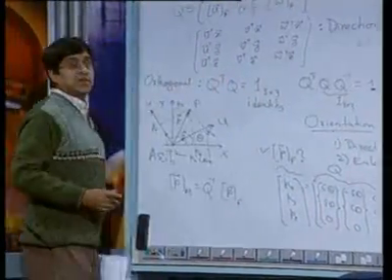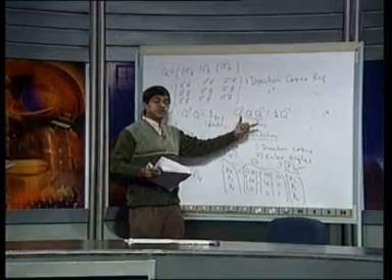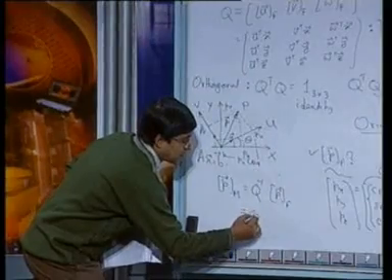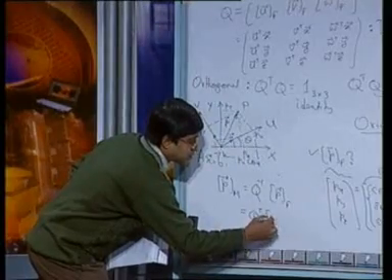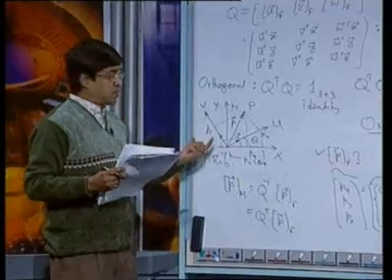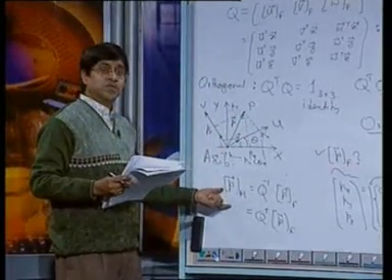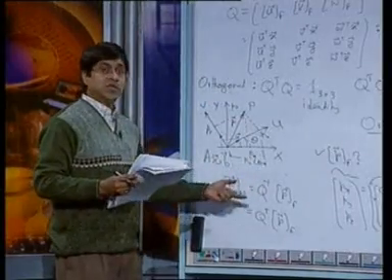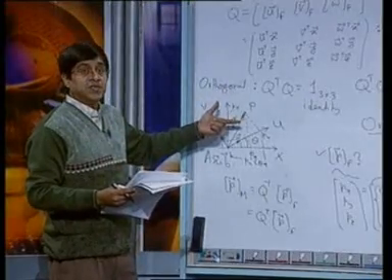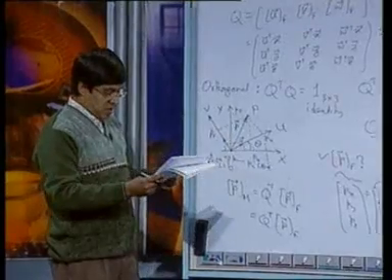from this one we can see Q inverse is nothing but Q transpose. This is because of the orthogonal property of the matrix. So, this is nothing but Q transpose P f. So, when rotation operations are involved, we can calculate one piece of information from the other by just taking the transpose. So, this is the direction cosine representation and a property of a rotational matrix. Next, we will go to